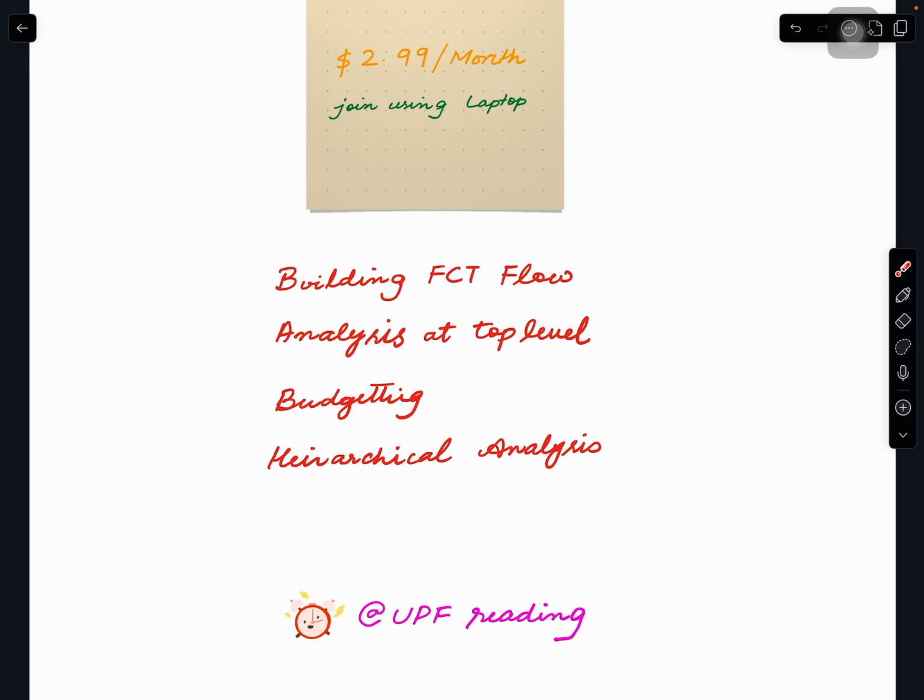I first explained why we need multi-VDD domains and why low power, and what different low power techniques we use. Among them, multi-VDD or lower VDD for certain cells is one, and then we can shut down certain areas and keep the other areas running, and that makes use of some other things like level shifters, isolation cells, and retention cells.